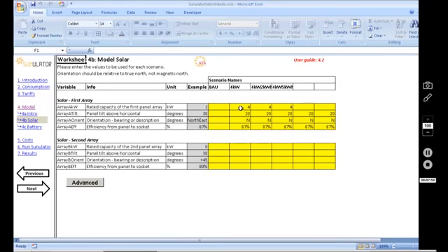However, once you get to solar panels spread out over that many different directions, then it's becoming a fairly generically oriented overall array of solar panels anyway. Your generation is going to be spread out fairly widely over the whole sunshine period of the day anyway, and you'll probably get pretty close by just modeling 2 arrays which are pointing in sort of average directions to cover the overall orientation of all of your panels.